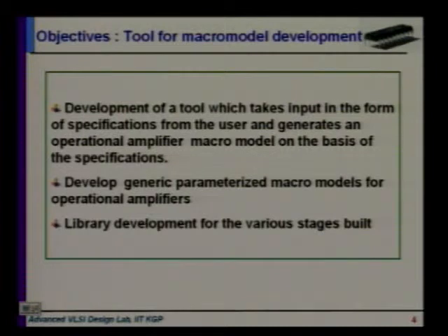What happens in actual design? Suppose there are a lot of transistors, you will go on changing some transistor W/L value. It may happen your gain is getting increased, but due to change of this W/L value, it may cause some other transistor to go out of saturation. So when you start this modeling, you divide the different specifications into different groups, different libraries. Each library should mimic different specifications. At the end, you cascade all those things, so the entire model gets developed.